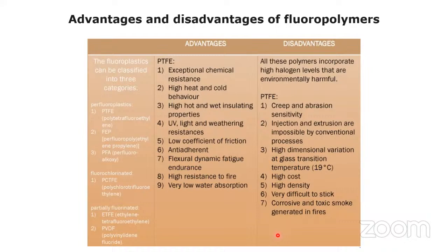So what are the disadvantages of these fluoropolymers? It is sensitive to abrasion. Then injection and extrusion are impossible by conventional processes. Whatever conventional processes we use for injection molding and extrusion of polyethylene or polypropylene, we can't use for PTFE or fluoropolymers.